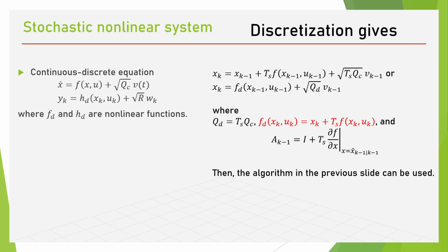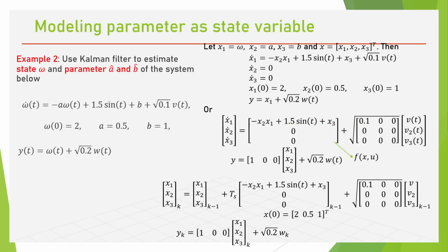So we just do the linearization, use the Jacobian linearization of the nonlinear function. So the Jacobian becomes a square matrix A here like this, and we evaluate it at the last known estimate. Okay, evaluate at the last known estimate, and then we just use this A for the normal Kalman filter algorithm. That's it, and we call it the extended Kalman filter.